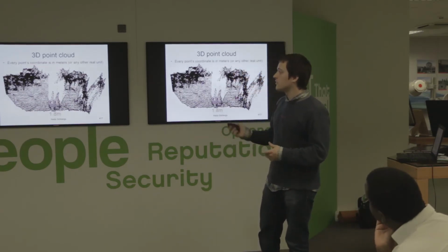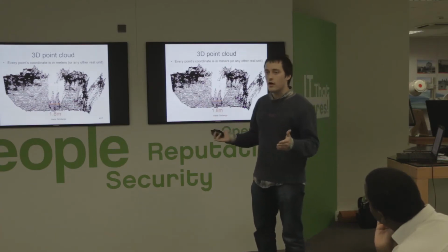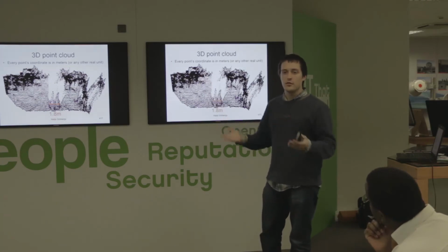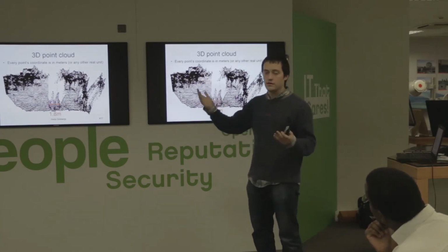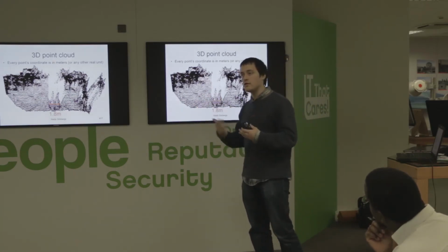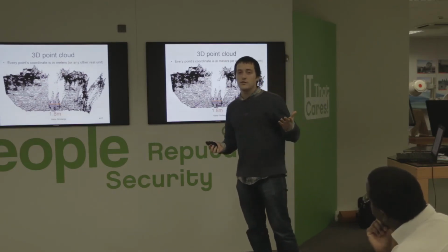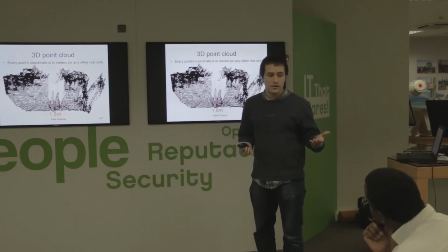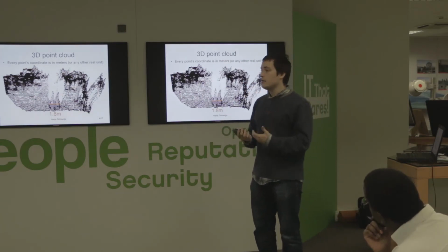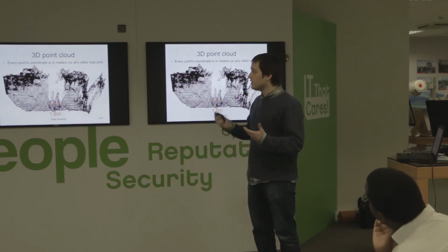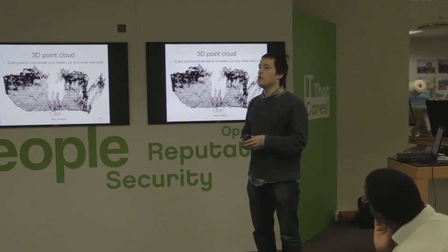So now if I want to see the width of the car, it is 1.8 meters. If it goes further away, it is still 1.8 meters, with certain accuracy and certain noise. And if I track that vehicle, then I know its speed in meters per second. So basically this data is a lot easier to use, for example in a computer safety system, which I will show later.